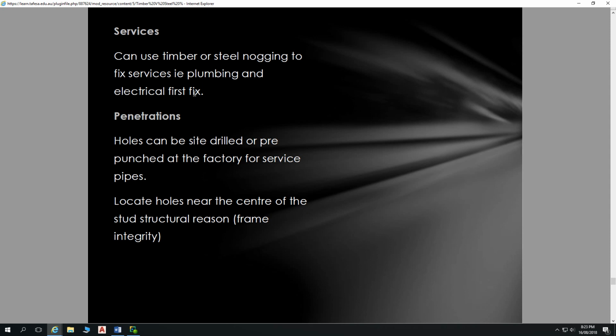It provides a lovely place to run hot and cold water pipes, and often that would go unnoticed because the screws go straight into those plastic pipes and form a nice seal around them, until that screw eventually rusts through in five to ten years' time, and then you've got an unexplained leaking wall. We had a bit of that come through the office.